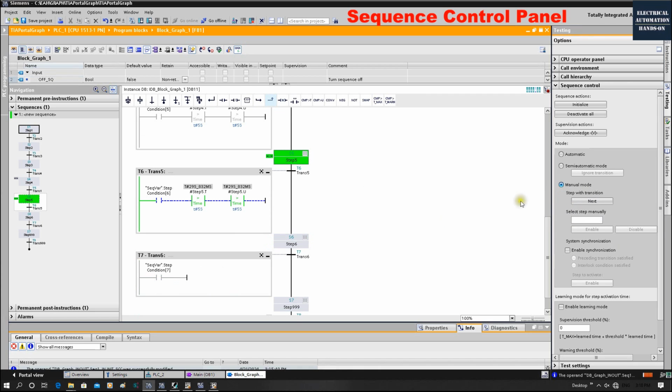It's very helpful. Another feature I would like to specially introduce is the semi-automatic mode. Try to imagine the early beginning of your commissioning test. You are waiting for some sensors or some servo drives to be in position, but in the real case, your sensor may be temporarily damaged, or the sensor hasn't been tuned, or your servo drive condition hasn't got ready yet. So now your sequence is being held here, right? Typically you can use the manual way to jump to the next step.